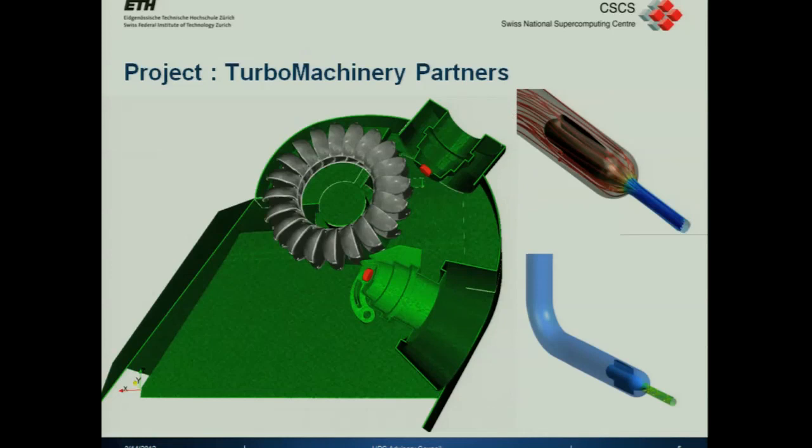They can have as many as 6 jets all around here, and if the water comes out there, splashes, and then lands on another jet, it disturbs the flow, which in turn causes the jets to spray out, which means you lose momentum. And even if you only lose a fraction of a percentage of the energy, it's actually megawatts that they're talking about over a period of months and years. So the water comes splashing out all over in this region, and what they want to do is put little plates in to just deflect the flow.